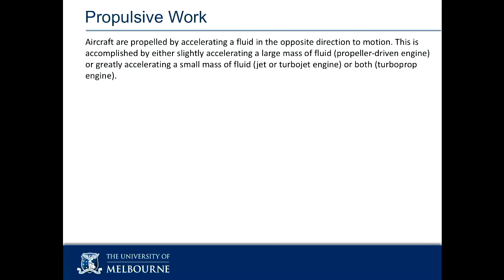As we were describing propulsion, I'm going through these concepts quickly, I understand. So as we were describing propulsion, I was saying that the main job of a propulsion engine is to increase the momentum of the fluid between what came into the engine and what goes out of the engine. So that's the way you get your force, that's where you get your thrust, your acceleration, is the difference in momentum in and momentum out, which is a little bit different to what we've been handling in thermo up until now, because we've just been handling heat transfer and work.